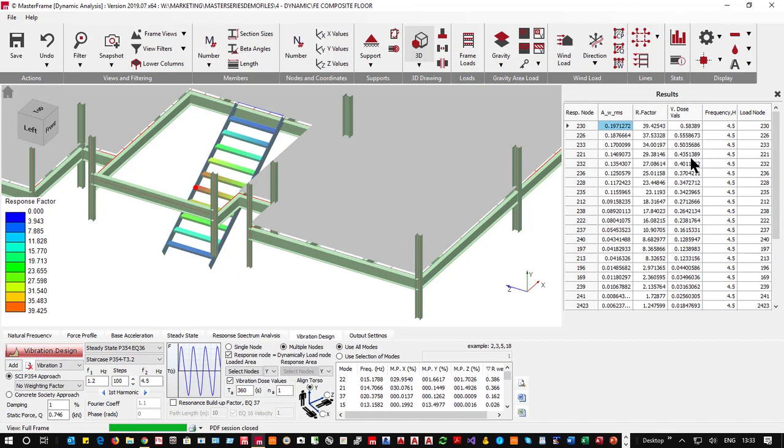0.6 is our dose value, and we're allowed, for a low probability, 0.2 to 0.4 from table 5.4 in the code. In this case, we're outside that range. We're up to a dose of 0.6. So 0.6 would be in the adverse possible, not low probability. So if you could accept, because this was very rarely used, you could accept possibly this higher dose value.